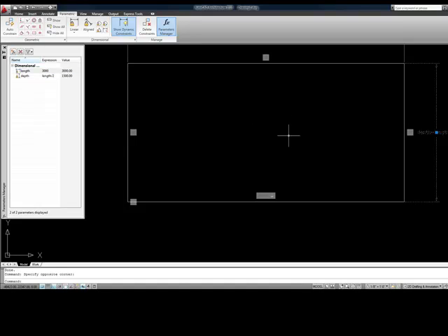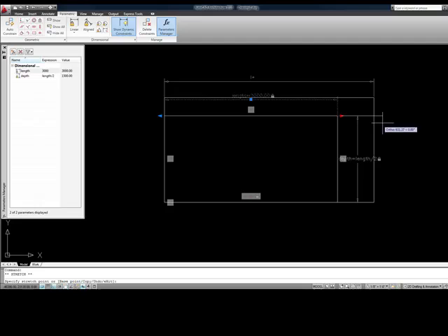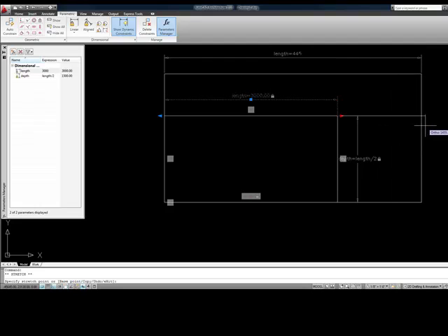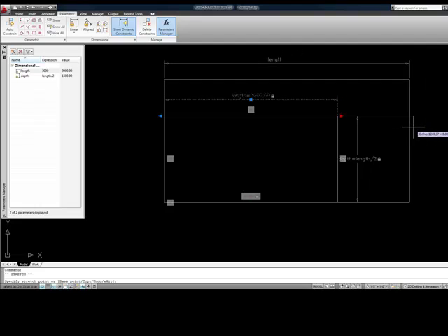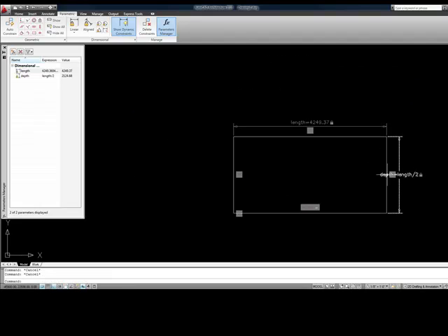And what that does is it makes sure that my geometry is always in a 2-to-1 ratio. So if my length is 3,000, then my depth is going to be 1,500. And I can see those values right here. So let's just look at what this means. If I select this dimensional constraint here, and I have some arrows so I can drag it, as I drag this over and I'm increasing the length, it's also changing the depth automatically.